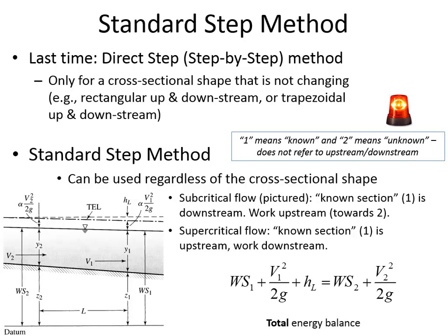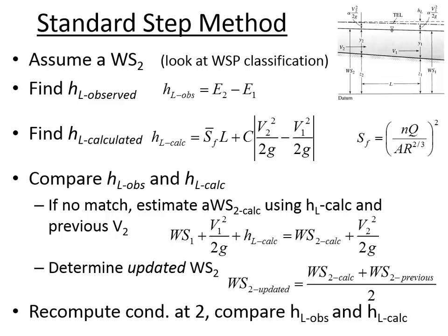This is a total energy balance rather than a balance on specific energy. Specific energy balance, remember, is when we're measuring energy above the channel bottom, but here we're measuring energy relative to a datum that's the same for both location 1 and location 2.